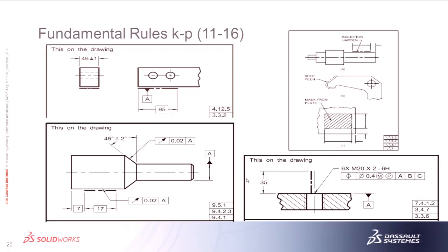One of the big things with this is we did a big cart that used a lot of tubing, and we had holes on the end, and we had other tubings or bosses that fit into the end of these pipes, and they're really long. But we needed to control some of the features on it. We had to specify how far to measure in, or how far that GD&T control went on the inside of that pipe, because if not, it meant the whole 10-foot pipe, and you're getting into stuff that's just probably not even feasible. So you really need to take that in mind. It's going to go the full length of stuff when you apply GD&T to it, unless you specify the distance.